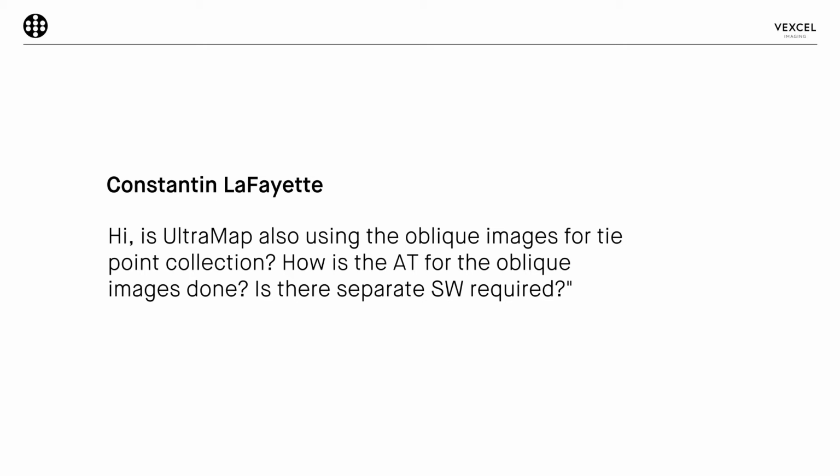Yeah, so UltraMap is using the oblique images, yes. If the data is captured with the Osprey 4.1 or also with the Osprey from the previous generation, this does not matter. Oblique images are always treated in exactly the same way. For the tie point collection, the operator can choose, depending on the project, if only nadir images should be used, or if all nadir and oblique images should be used.